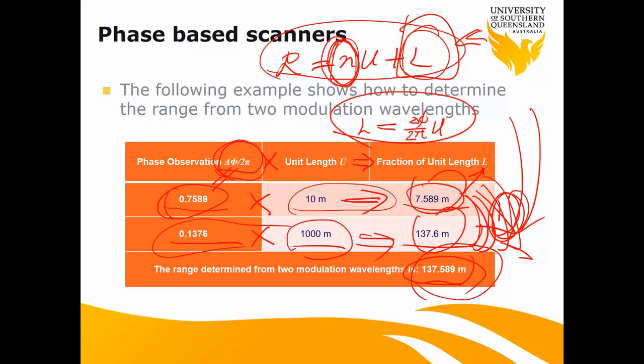But remember, we still call this a single frequency laser scanner. Why? Single frequency means just one carrier wave, but we have some modulated signals, like GPS. We have single frequency and dual frequency; back to this case, one carrier wave with two modulation waveforms. So it is still a single frequency laser scanner. But we do currently have dual frequency or multiple frequency laser scanners.